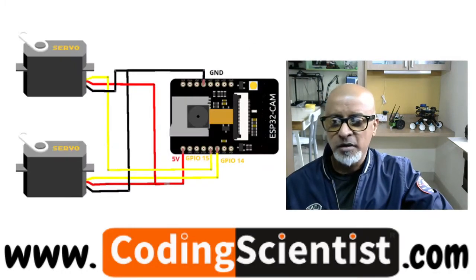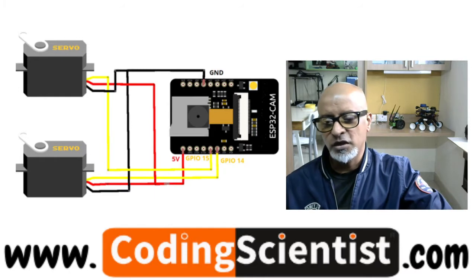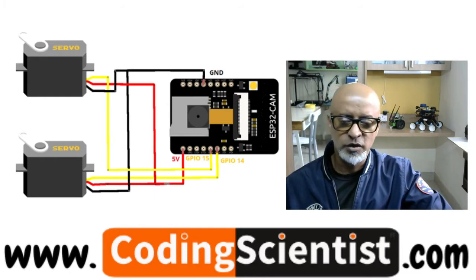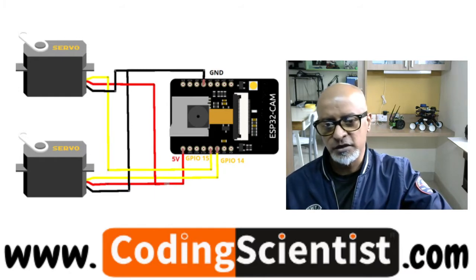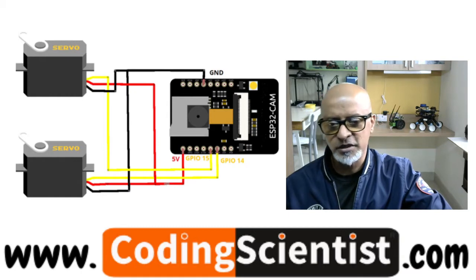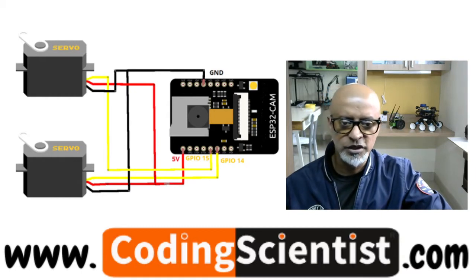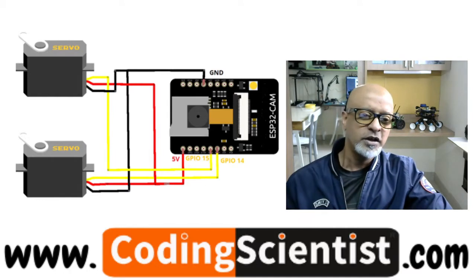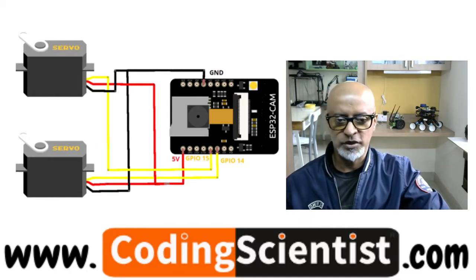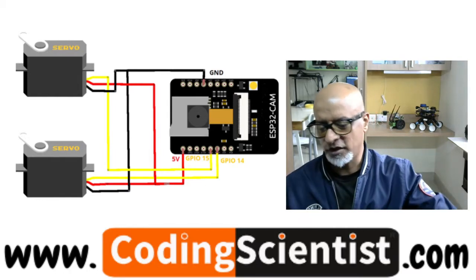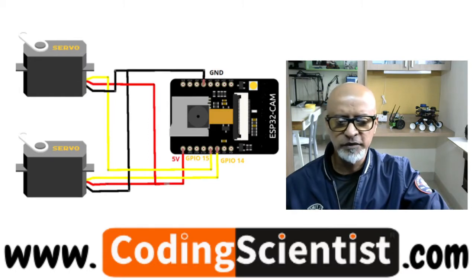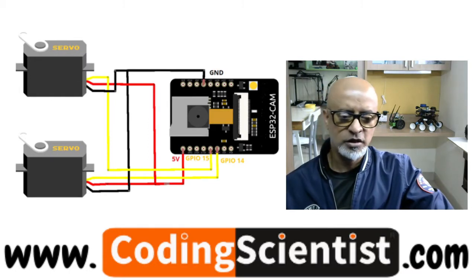Go ahead and build the circuit like this. Your two different motors, of course. The positive and the negative, which is the ground, and the VCC pin is the common pin, and the signal pins are the yellow lines, which are connected to your GPIO 14 and 15 of the ESP32 cam. So that is where your signals get triggered, right? Now what we will do is, let's take a look at the code, guys.